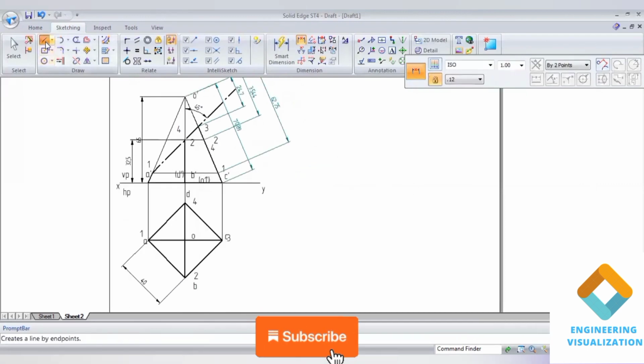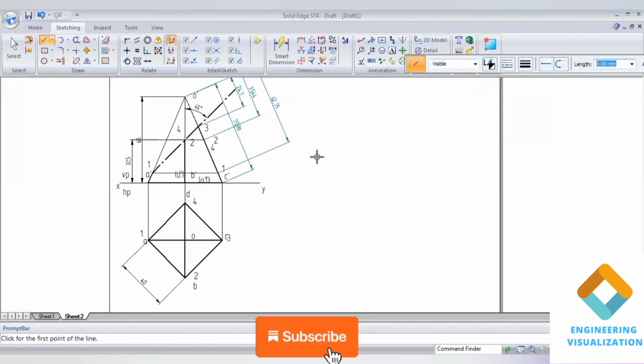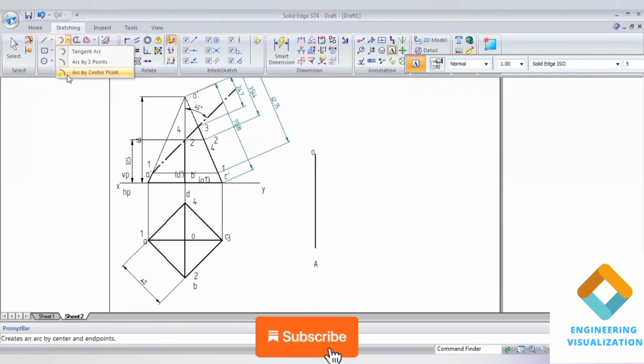Now we will construct the same slant edge length here. After drawing a vertical line, we need to draw an arc using the arc by center command. Okay, use arc by center command here.